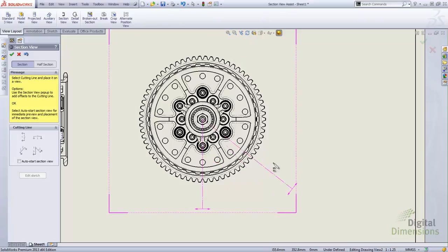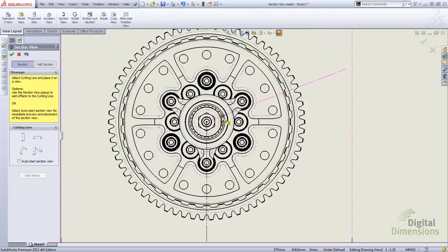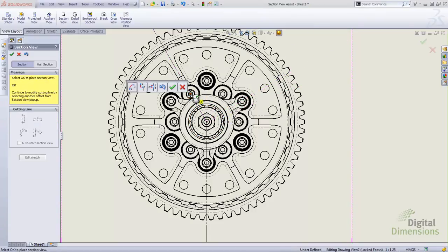My first one will be a vertical, so I bring it until I get my vertical relation there, and then I go over and go and grab one of the next points here. So notice that I am hovering near the edges for the moment, so it'll snap to the center. Allows me to get the point right into the axis of one of these spots there.